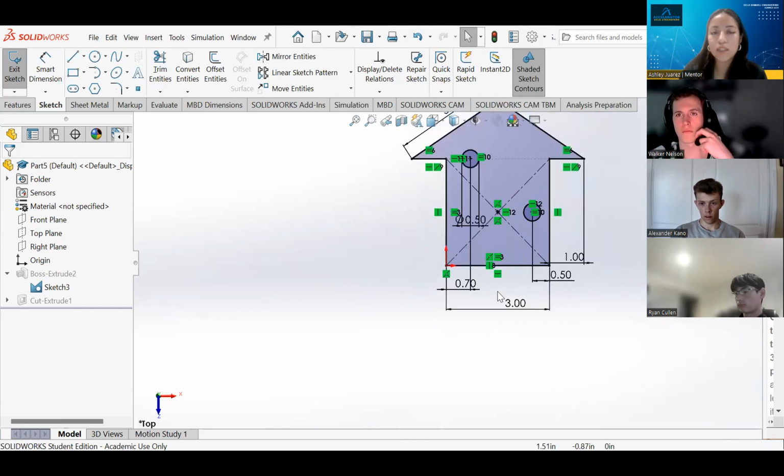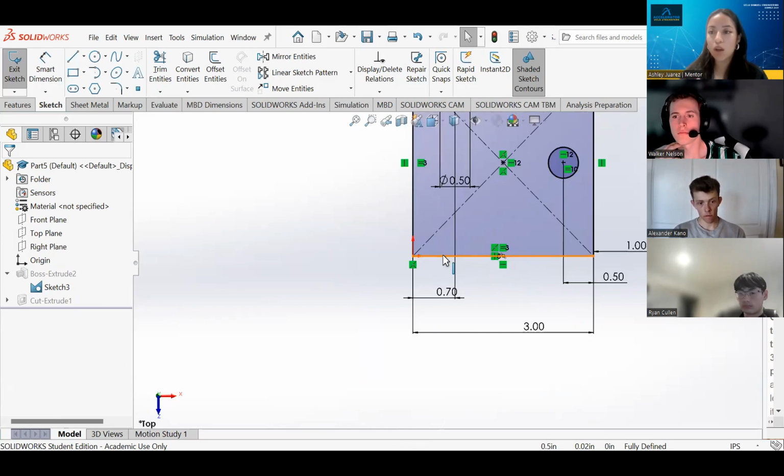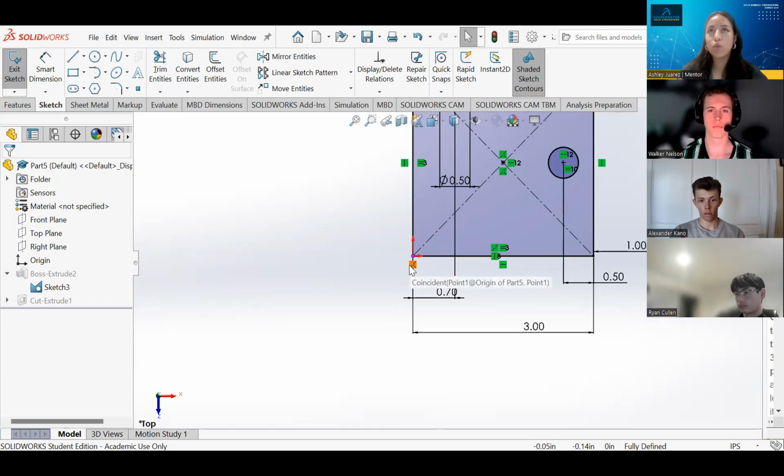And so when it's creating its planes, it's in relation to that origin, the origin that's smack in the center of all 3 planes. So that means if I want the right plane to go through the center of this house so that I can mirror this feature, I have to switch this origin, which is sometimes why you can't always just place the origin wherever you want. If you want things to be easier, your origin should be smack in the center of whatever it is that you choose to do.